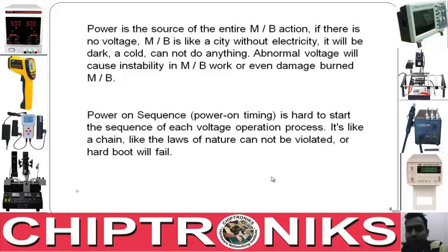You will always see in a notebook that voltages at all the points are fixed. They never have to change. The voltages are fixed, and you can call it a law of notebook motherboard. In a notebook motherboard, the voltages which are specified on a schematic diagram will never change. And how they get voltages, when they get voltages, this is all about power on sequence. So when a notebook motherboard traces its entire power on sequence, then the hard start is finished, and after this hard start, the soft start will load.